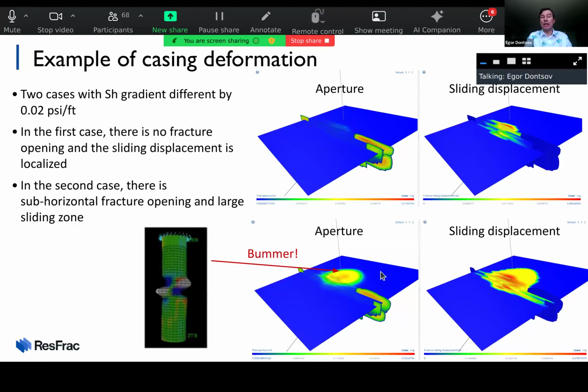And so this horizontal fracture doesn't feel the vertical fractures, doesn't feel the shadow from them. So it's a single fracture essentially in intact formation. And so you give it a few hundred psi, and now it opens and propagates almost forever because there are no barriers. So there is no warning light, you know what I mean? You have no horizontal fracture, no horizontal fracture, and then suddenly you increase pressure just a little bit, and now you can potentially have a large scale horizontal fracture. So that's something to keep in mind.